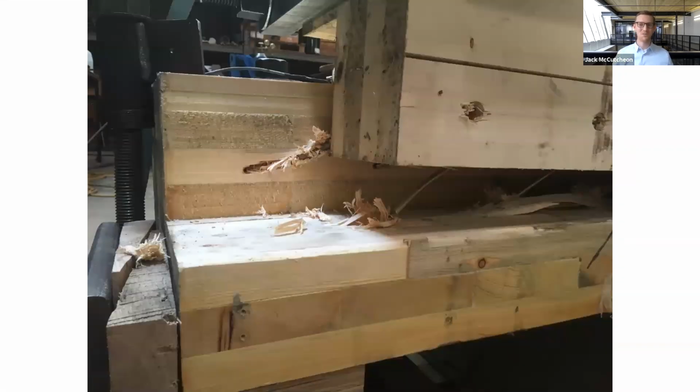Now here's the ultimate failure once we just blew this thing out of the water, right? So the failure mode for this connection had these screws that actually pulled through the wood and yielded in a very ductile way. Now in a seismic event, this would never happen. We would design this connection to stay essentially elastic while all of the deformation and ductility is provided by those hold downs.